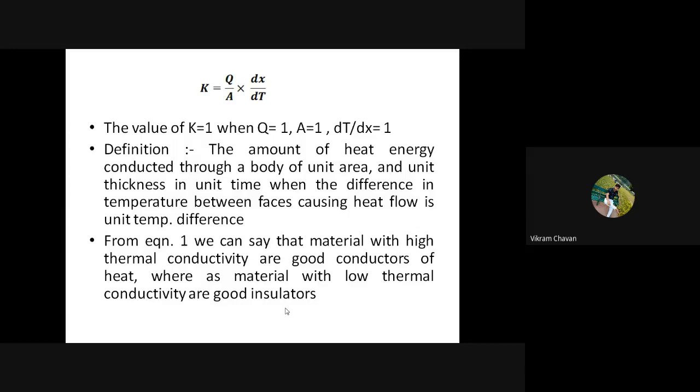Okay, so wood is an insulator. We can say that rubber is an insulator. Cotton rope is an insulator which opposes the heat transfer. That is nothing but what? The rate of heat transfer through the material is very less. Why is this rate very less? Because that particular material's thermal conductivity is very less, and because of that, the heat transfer rate through that material is very less.